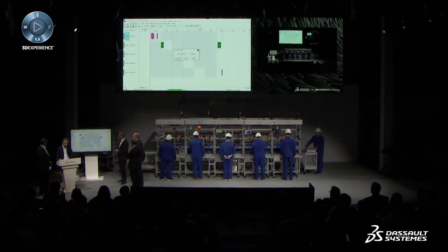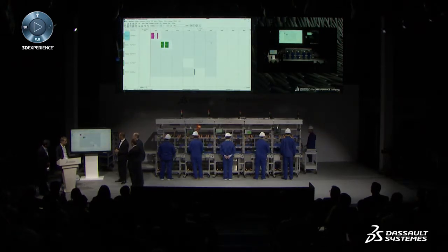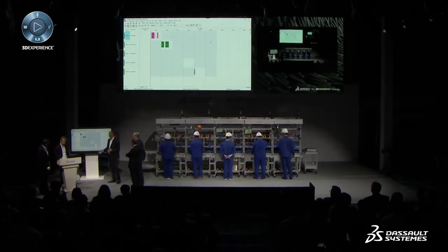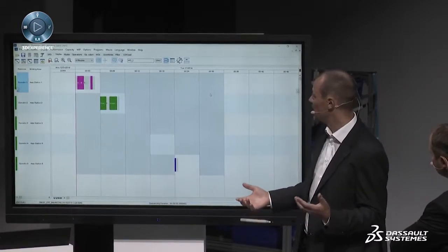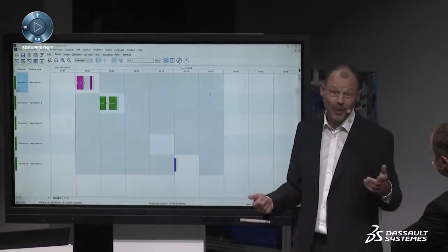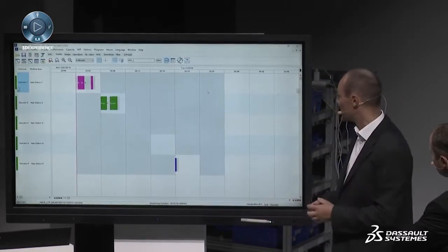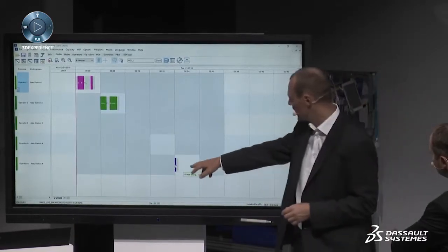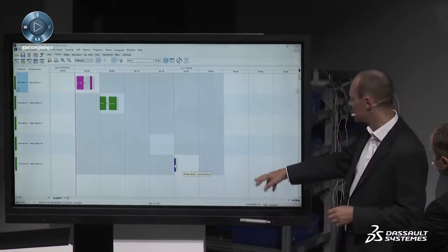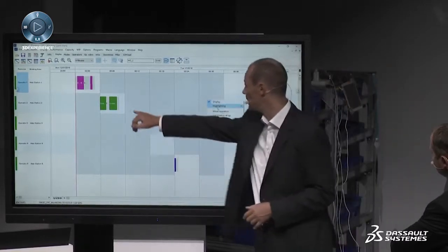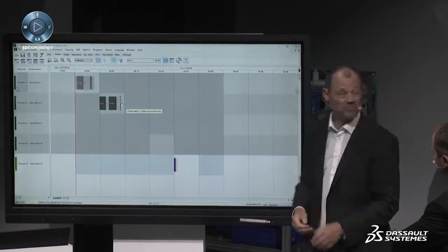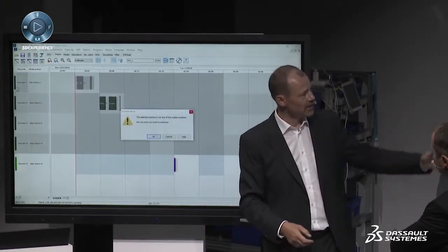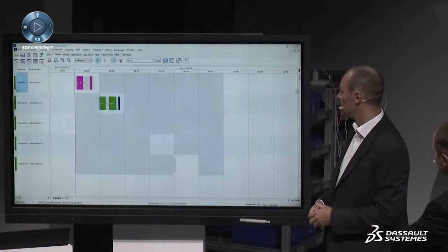Yeah, almost good. It's good. This is not bad because we now have a way to go on with the production somehow. We can do it in stations 1 and 2, but maybe we can optimize the next step a bit, because we see here in station 5 there is still a small process, this label printing, and I think because we have a little time here, we can move it directly to the operator on station 2. The line is not too big, so he can take this label and put it on station 2.